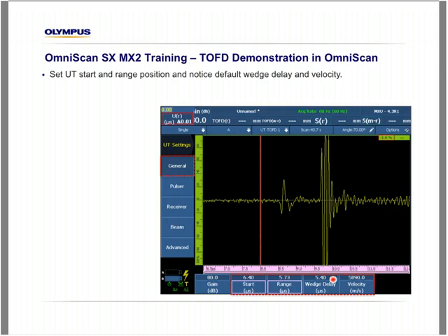Using the most common Olympus wedges for 3 to 6 millimeter probes, the Olympus STI series of TOFD wedges, this wedge delay for flat plate or girth weld parallel surface inspection will always be between approximately 5 and 6.5 microseconds.